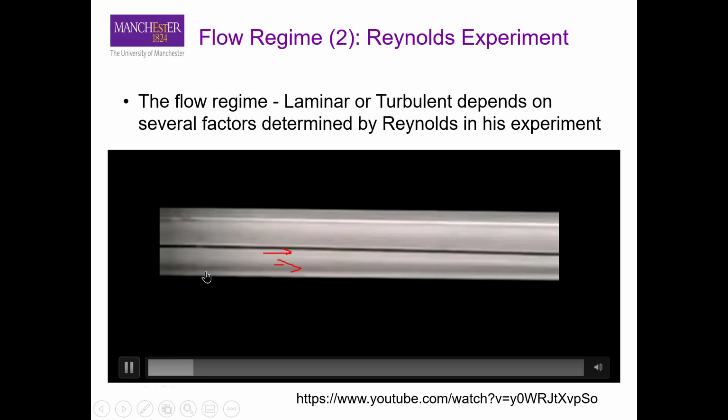So at this point, the velocity is much lower, and you can see that you don't really observe anything, but actually water is flowing in this channel. And if you increase the velocity of this fluid, outside fluid, you start to get this disturbance just like the faucet as I explained, okay? So when you increase the velocity higher and higher, you get this disturbance, and now the liquid is going from a more structured flow towards turbulent flow. So at the moment we have a transition region, and then if you increase the velocity of the outer fluid a lot, you have a complete disturbance or intermixing of different layers of fluid, and that's what we call turbulence.